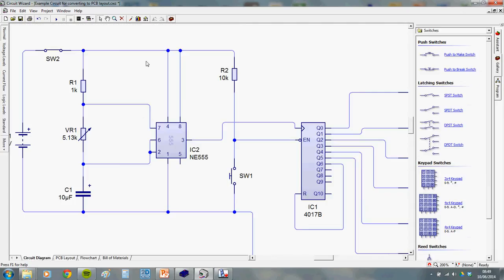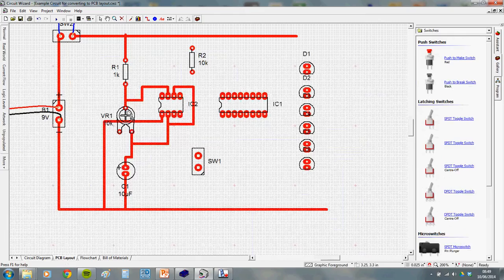So pin 4 and 8 now need to go up to positive. This is the positive rail, but they need to go to the bit of the positive rail that's after the switch. So here's the switch, this is the positive rail after the switch. Right, 8, we can't go up that way because we'd be crossing, but we could come through here, like so.